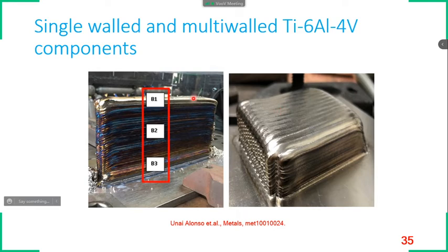I was previously talking about decolorization of the material. If we do it in an open atmosphere, what may happen? The metal will tend to decolorize. Here we can see the titanium has decolorized into a bluish green color. This decolorization is mainly because we have fabricated in an open atmosphere, due to which atmospheric oxygen gets attracted and the metal becomes decolorized. If you do it in a closed chamber, this kind of decolorization issue can be avoided.